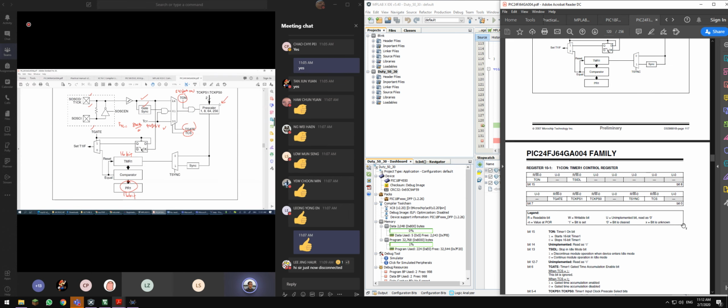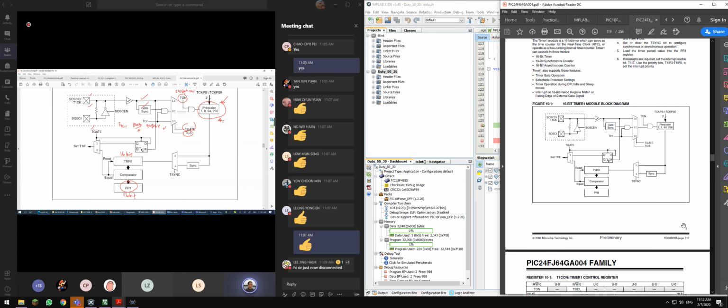And of course, this is the prescaler. So whether you want to reduce the frequency or not, if it's too fast you reduce the frequency; if you don't want to, just remain as it is. Let's say at the beginning this is 0, 0, 0, 0. This will start running.